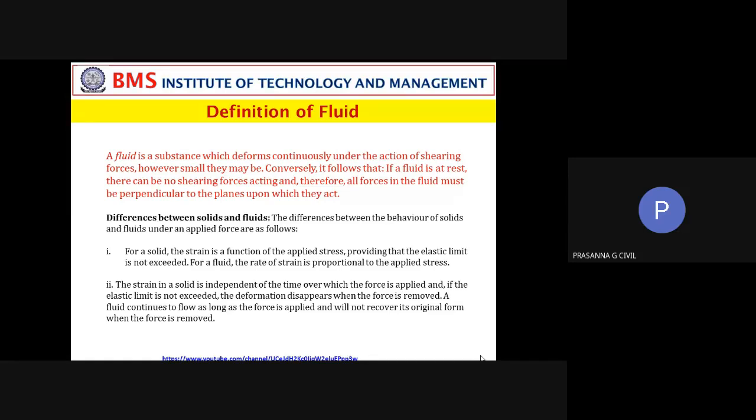So conversely, it follows that if a liquid is at rest, there will be no shearing forces acting, and therefore all forces in the fluid must be perpendicular to the planes upon which they act. So that is the definition given for a fluid. Now, this is just for understanding's sake. What is the basic difference between solids and fluids? The difference in behavior of solids and fluids under applied forces. When you differentiate them, you are differentiating them based on the influence of forces on them.